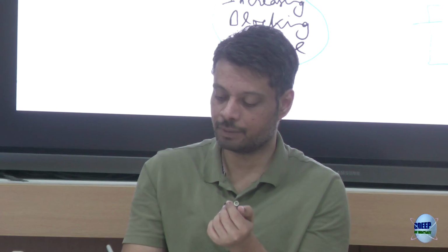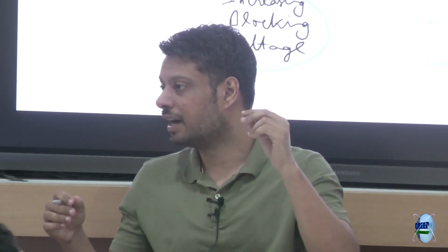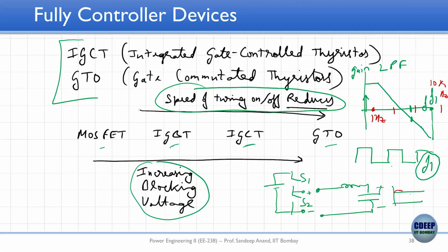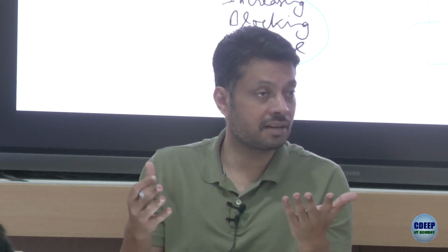So, what he is saying is that if you have a fixed low pass filter like this one which I have drawn, and you choose a higher frequency, you get more and more attenuation. So the output voltage is a more refined DC voltage. If you use 10 kilohertz, it is better. If you use 100 kilohertz, it's maybe even better. You would have negligible high frequency passing through that filter. It will be mostly DC. Of course, it will have some small ripple at the output along with the DC value. That ripple becomes smaller and smaller if you keep using larger and larger frequency. So it makes sense to use larger frequency in general.